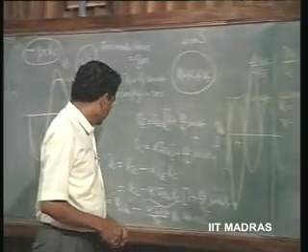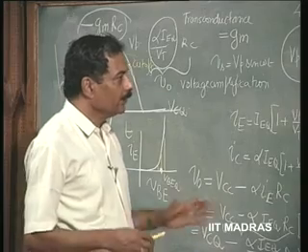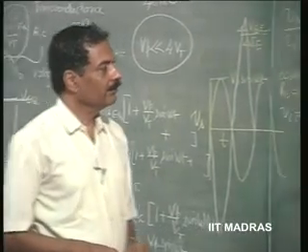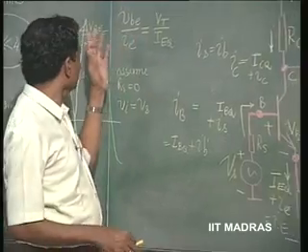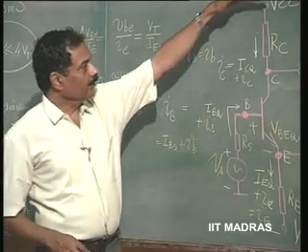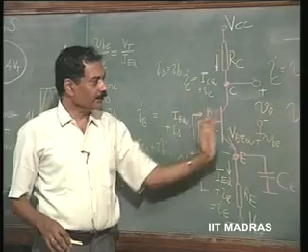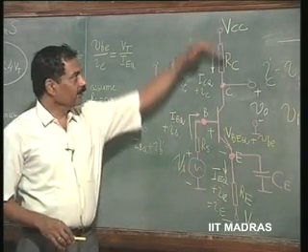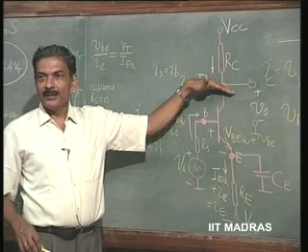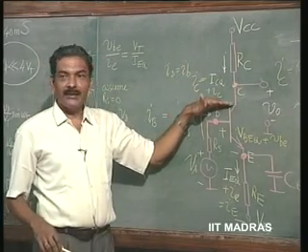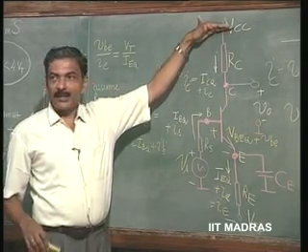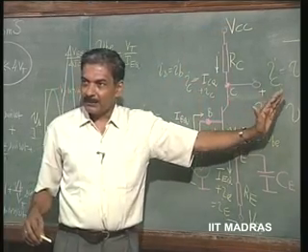So, this comprehensive thing is important in that in the initial stages, when these nonlinearities do not come into picture, when this system can be assumed to be linear, when this Vp is much less than 4 times Vt, then I can say that I will have one circuit for DC, another circuit separately for AC. This is VCC and there is no change here. At this point there is a change, V0 is possible, because current IC is changing here and that is flowing through RC. So, for all changes, increments in voltages, I am going to set up a separate equivalent circuit.